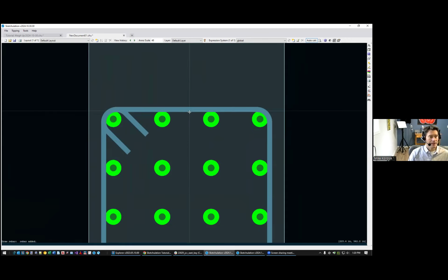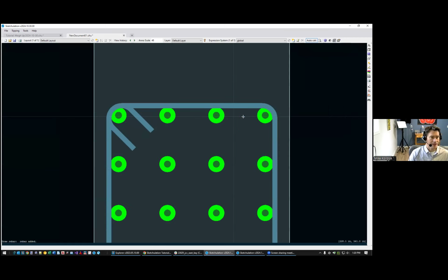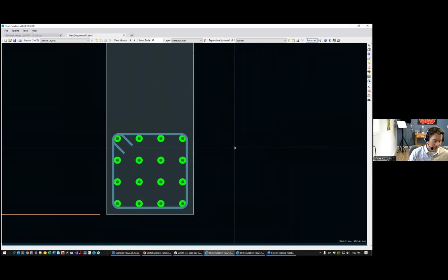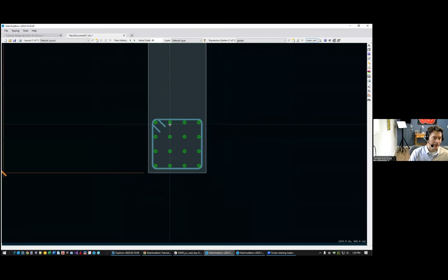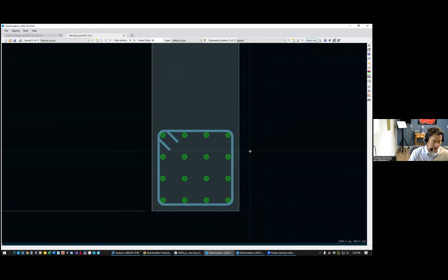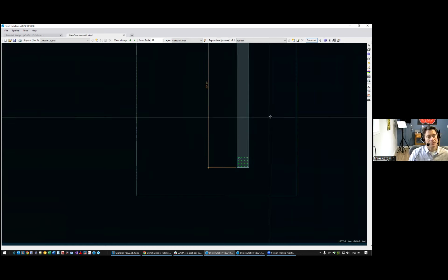Okay, so quickly there I have my pattern. You'll notice that the lines are sort of intersecting. That's because of the thickness of the layer, and that can be adjusted. You can also type in the thin lines command, and there you see that none of the layer thicknesses apply. So now you can kind of see exactly where things are laid out. But for graphic purposes, you normally do want that thickness to show, and so that's how we'll leave it for